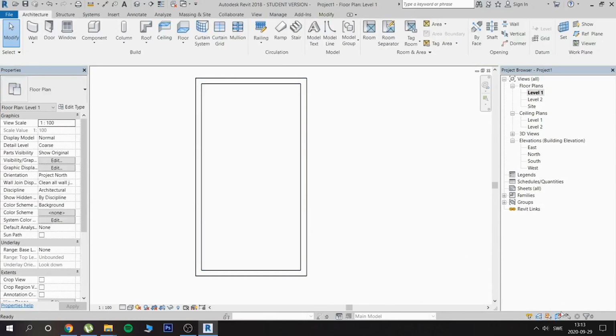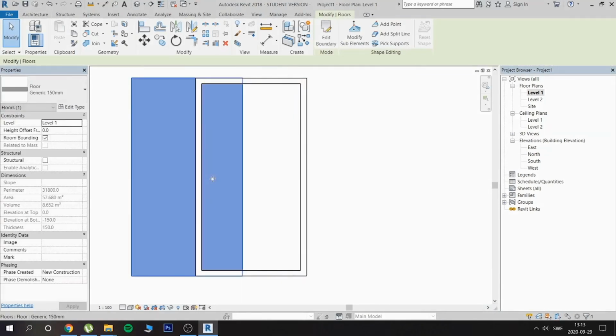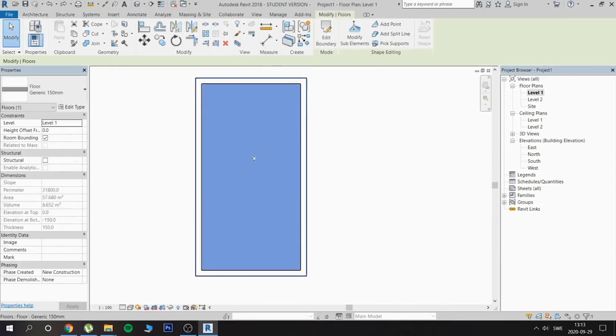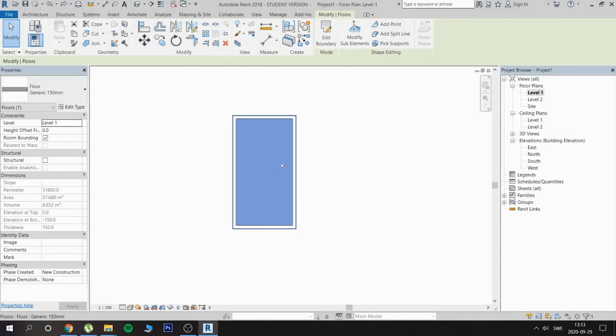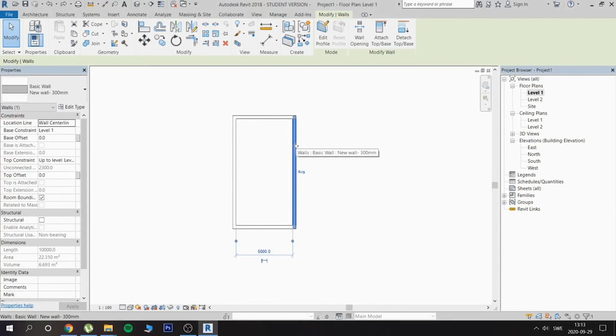If you click these icons down to the right, you can actually select the floor through the level. And as you see here, I can't select it. And I simply click this, and I can tap on the floor. And you can drag it like this, which I don't really recommend. It's always better to use numbers when you're changing things in Revit.